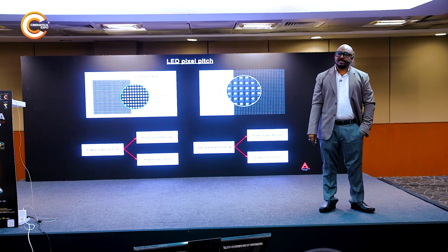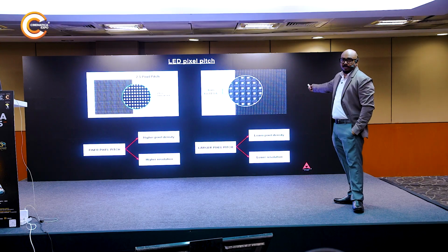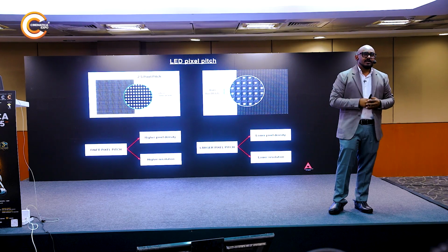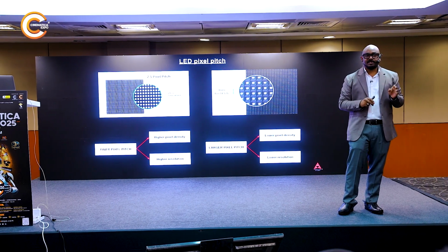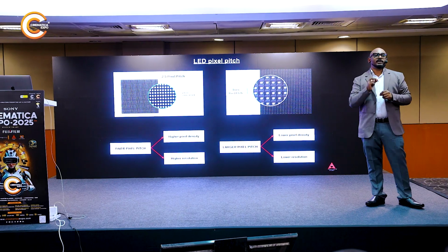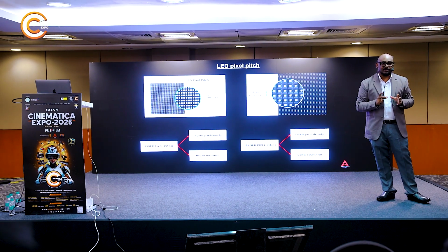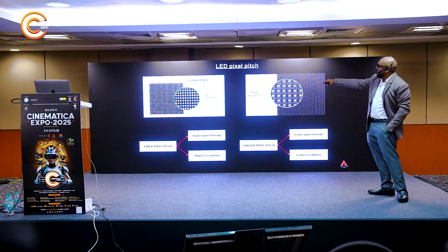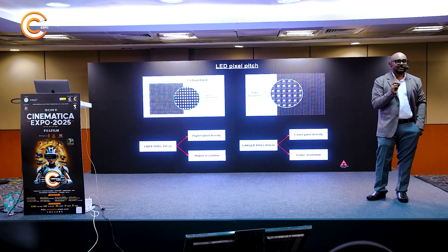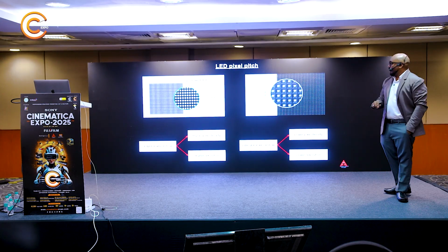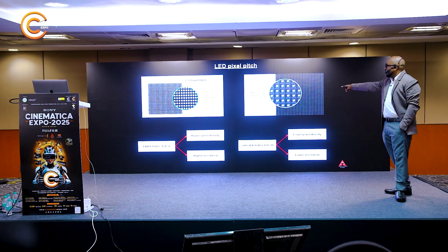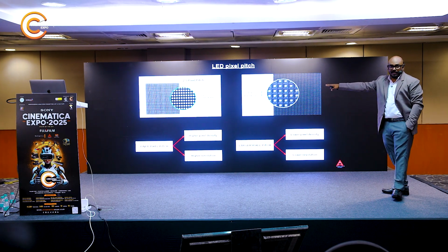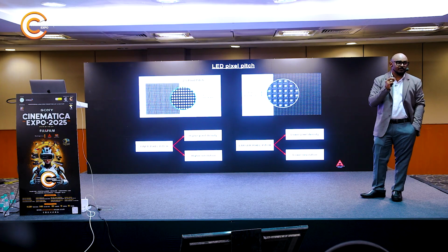All right. So basically, even this LED is made of tiny pixels. And any LED worldwide is measured in pixel pitch. Pixel pitch is nothing but the distance from pixel to pixel in one particular cabinet. You can see there, that's a 2.5 pixel pitch, which means the distance between pixels is 2.5 millimeter. And here you can see a pixel pitch of 4. You can observe the distance is more when you compare with 2.5.